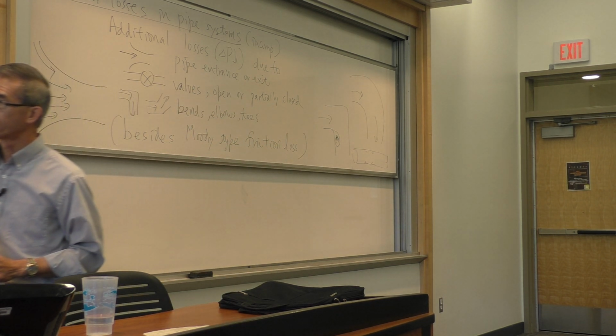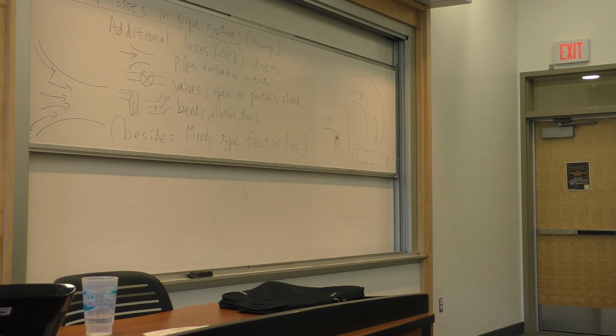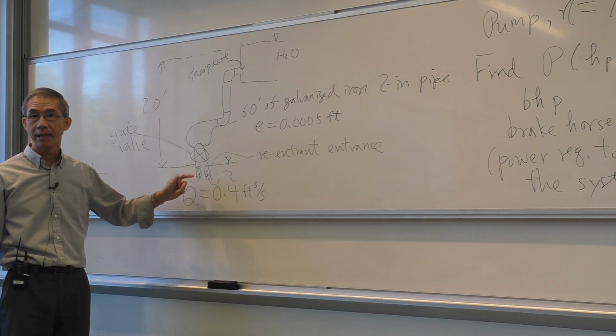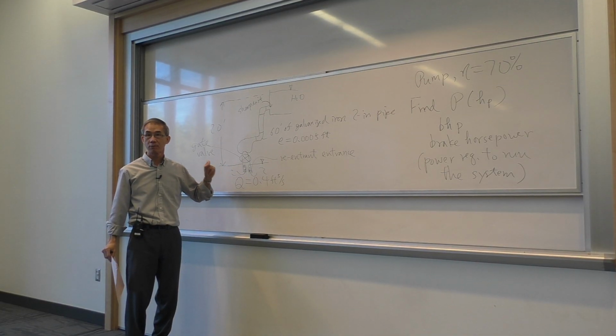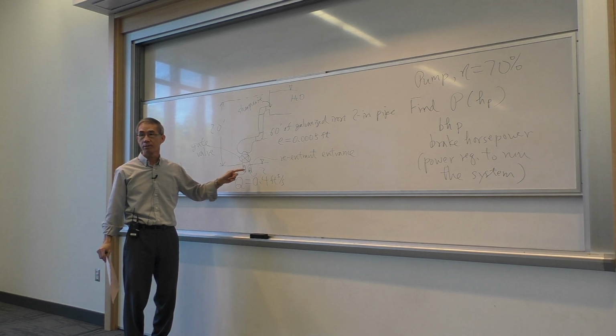Like for that intake, because of friction, the flow will separate and create some losses right at those corners. Because the real flow with friction cannot negotiate a sharp corner. And that kind of separation is what we are trying to account for, and you pay for it.